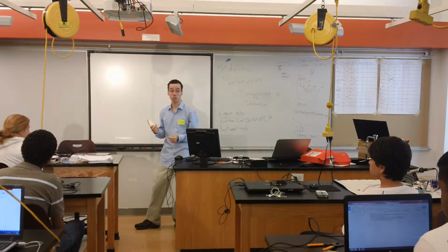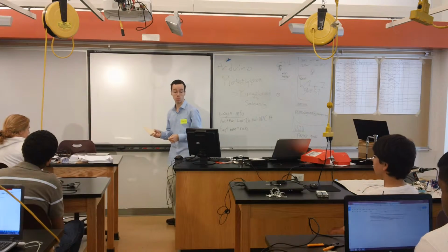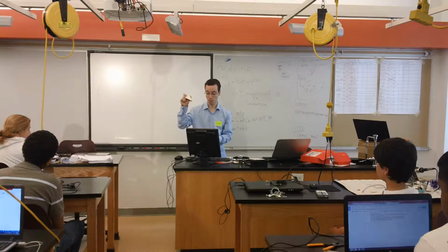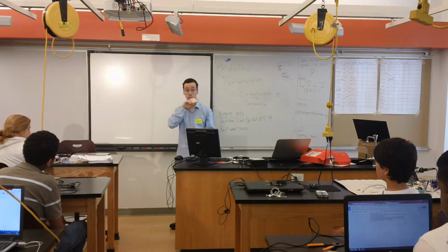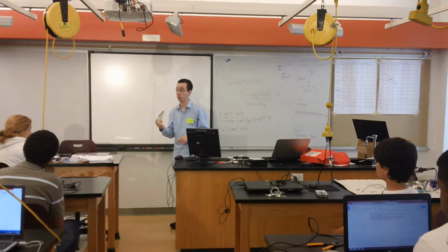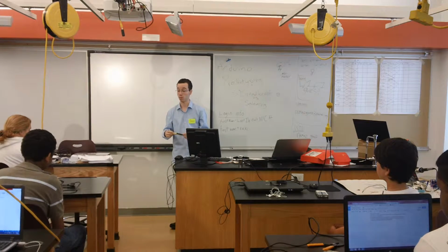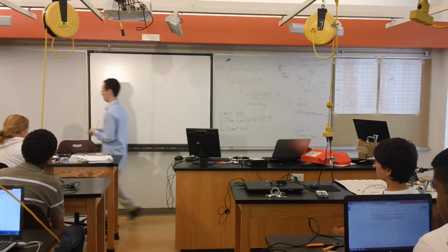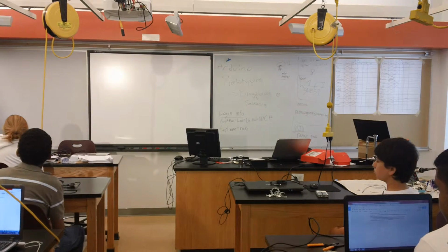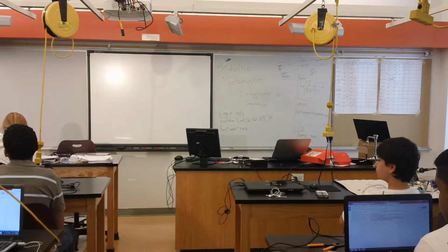So I'm going to show you the basics of how you make and dimension those drawings, and then I will bring up a schematic in AutoCAD of a part kind of like this, and have you guys try to walk me through doing it, and see if we can get all the right dimensions. So the goal is, when I put up a picture of this part, I'm going to real quick draw a sketch of it, and then show you how you would dimension it.